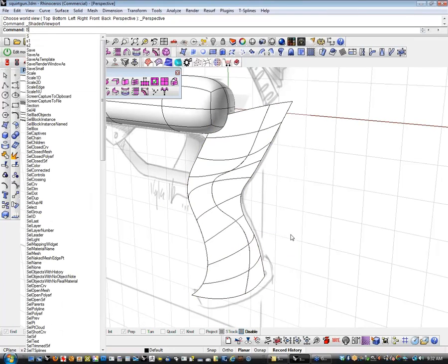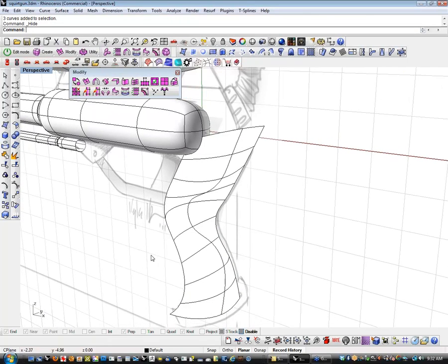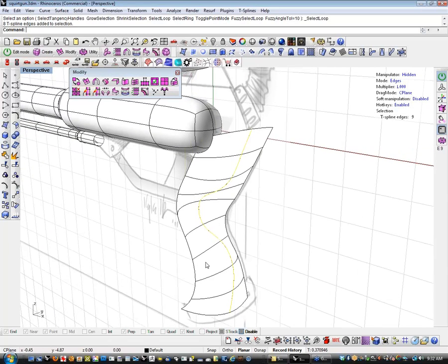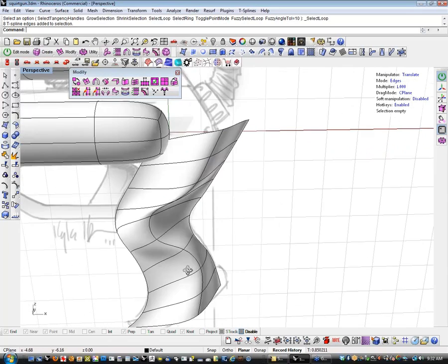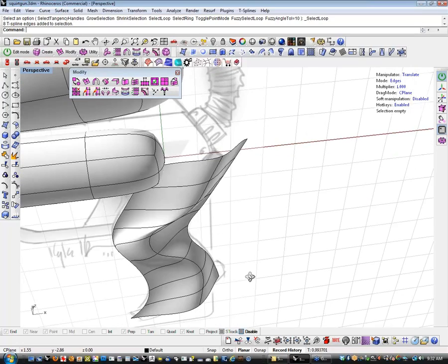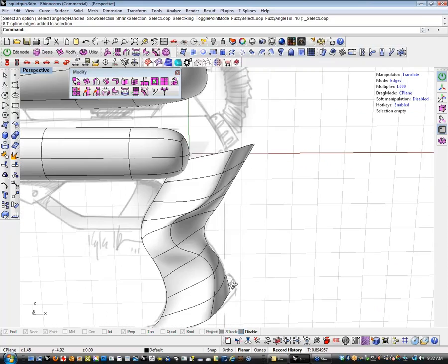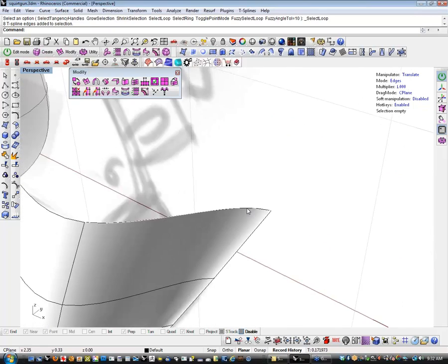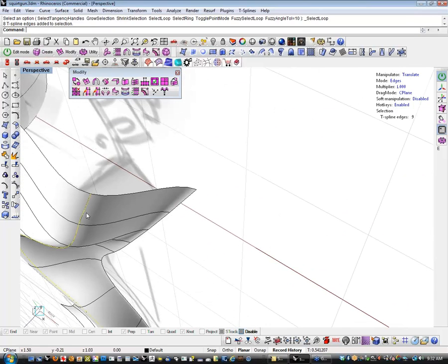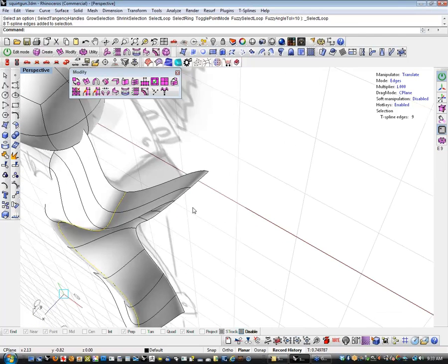so that all I need to do is, let me get rid of my curves here, this is an edge loop now. Come back here. This is an edge loop now that I can pull, and my form starts showing up. So basically all I need to do is just start messing around with this thing and adding or deleting edges to get this out. Now you'll notice something that's going on here. Check this out. See this return right here, and it's really obvious the more I pull this thing out. Burp. See this curve right here? That's not what I want. I actually want this inflecting tangent going towards the other direction.